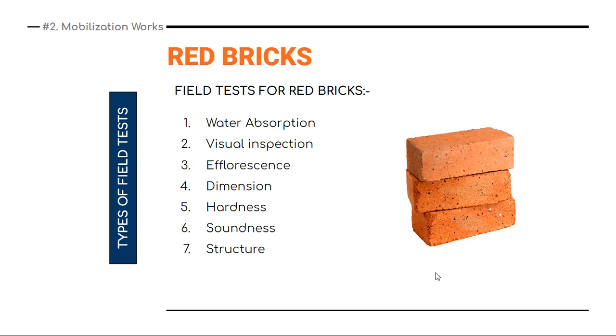Then the fourth part is dimension. This is quite important, a very important test. This field test will be explained in more detail at the end in our field visit tests. Here, you need to take 20 bricks at a time. You need to arrange them together, and check the dimension of the entire brick size in mm.